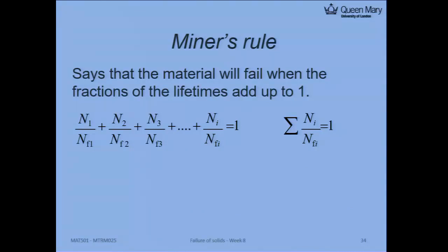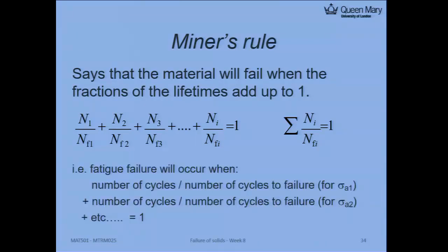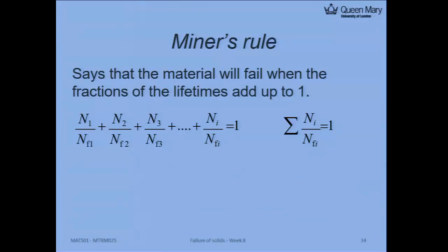So what I'm saying is, this is one type of stress amplitude you applied. It gives you some damage. It must be smaller than 1. And this is similar, another stress amplitude. So adding different amplitudes together then gives you the final damage. Once it reaches 1, then there is failure. I'm not sure you understand that well, but let me give you some more examples to help you understand what happened here. So basically, we're looking at the damage. If damage equals 0, that's no fatigue damage. If damage equals 1, that's full damage, completely damaged. And when we're applying different stress amplitudes, you generate a small amount of damage. In the end, you accumulate them together until they reach 1.